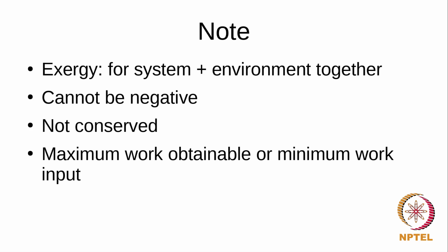What we can also define it as is the minimum work we have to do in order to take the system from the dead state to whatever its state was. So both of them are equivalent. The maximum work you will get is essentially when it is reversible. When you are going from its present state to the dead state, the maximum work you will get is when the process is reversible.